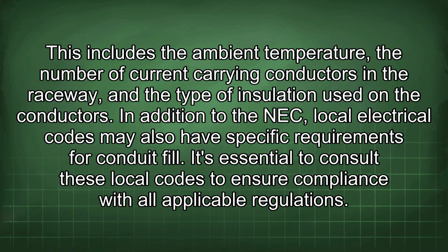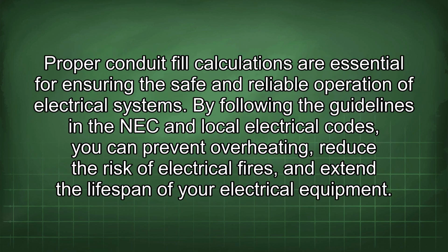In addition to the NEC, local electrical codes may also have specific requirements for conduit fill. It's essential to consult these local codes to ensure compliance with all applicable regulations. Proper conduit fill calculations are essential for ensuring the safe and reliable operation of electrical systems. By following the guidelines in the NEC and local electrical codes, you can prevent overheating, reduce the risk of electrical fires, and extend the lifespan of your electrical equipment.